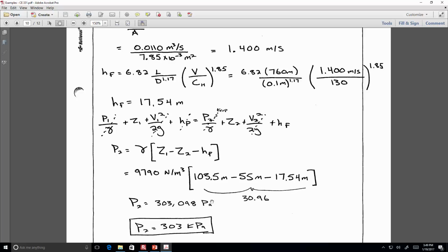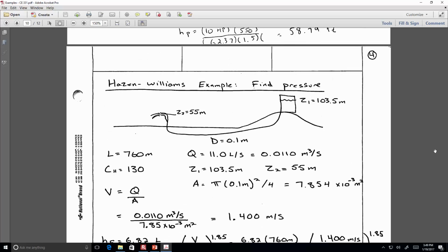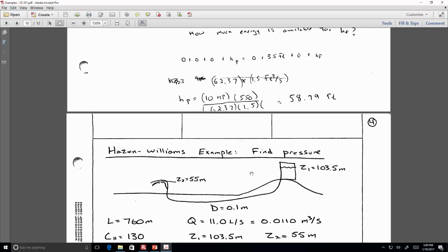I know in fluids you told us to assume 9810. Now where this is outside, are we supposed to assume 9790 to do that? Well, as long as you just state what assumption you're making, then that's fine. I mean, there's different arguments to be made. You know, the water that is going to be coming out of a pipe that's underground is probably going to be pretty cool, I think maybe around 55 or 60 degrees, and so you could look up the unit weight for that. Maybe the 9790 corresponds to a little bit warmer water, and I think the thinking there is it's in a tank, and so it's warm from having been in the ambient air.